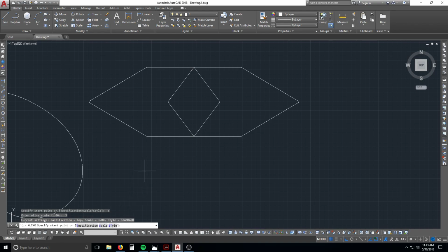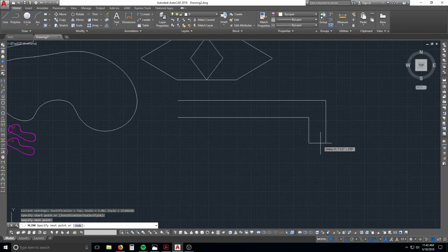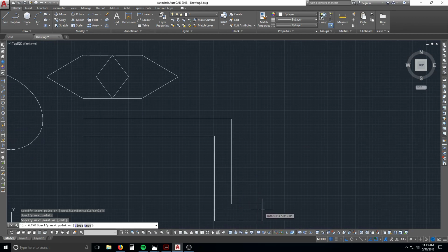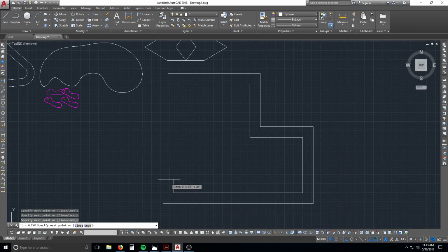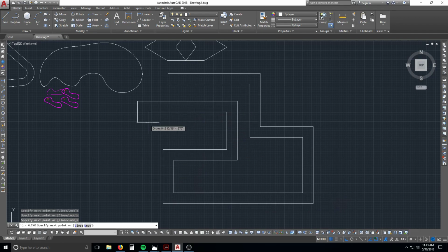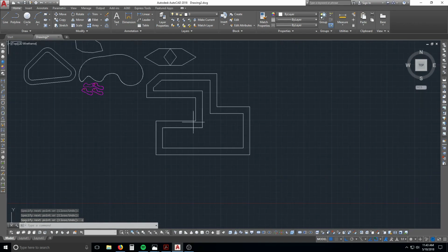So now what you can do is you can click here. See how it's drawing 2 lines at one time, and it looks like you can draw a house really quick like this. There, there, there, there, there, there. If we come up, watch this here, and if you remember that close command, C, enter, how it did it for you. And that's a polyline, both of them together.